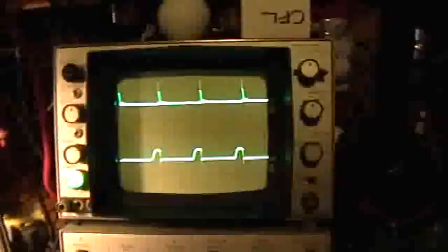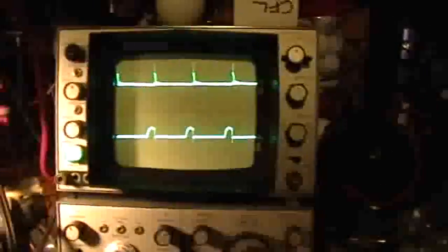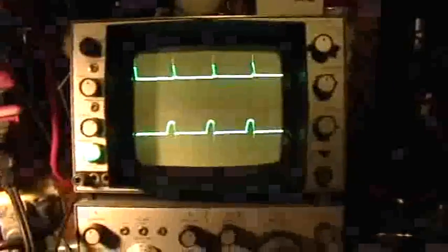There. Now I've removed that resistor and we've stayed in this second mode. Whoops. Let's get it back. Okay, so I just flicked it with the resistor again. Come on. Maybe need a little bit more voltage there. Okay, so now hopefully it'll stay in this second mode here. The frequency there now is down to about 10 kilohertz.